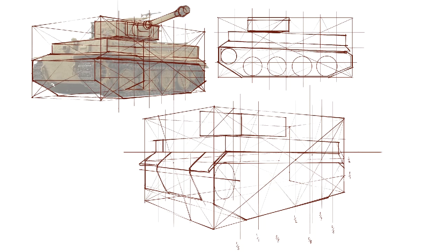I want to make sure that the contact points here and here are vertically aligned, so that I do know that this ellipse, despite being so narrow, does actually represent a circle in 3 dimensions. And that's very important for our driving wheel, or driving gear, or whatever it's called. And I turn that into a cylinder. Same deal, I also have to test this one to make sure that its contact points are vertically aligned.